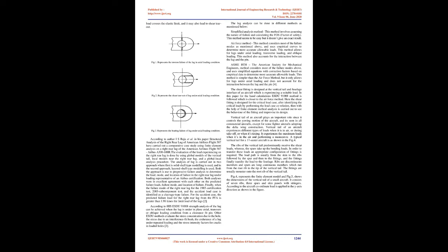Margin of safety for lug joint is computed using two methods: max peak stress and stress averaged over the contact area, but in the max peak stress the predicted margins were much less than those calculated from the theoretical calculations. The shear fitting transfers the shear loads, but it is critical due to axial loading.